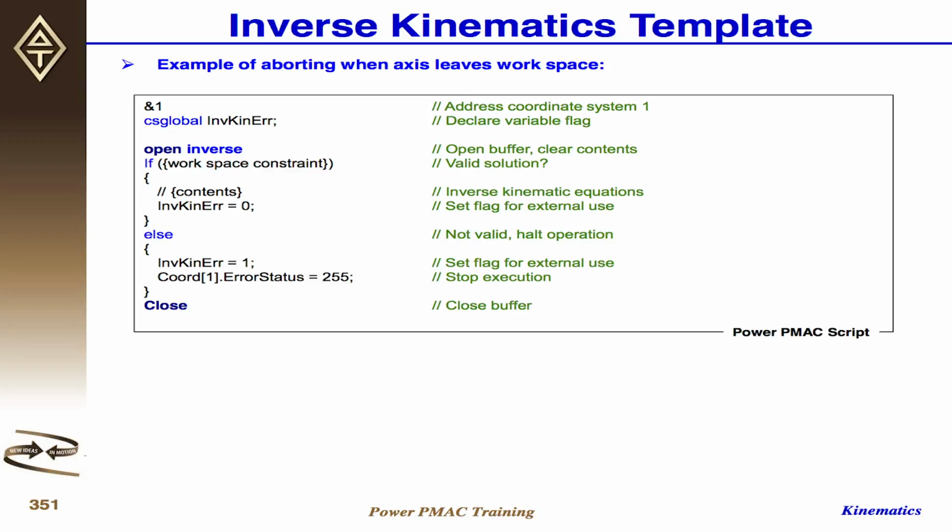Okay? So you have to make sure that you have the logic inside. Make sure that the mapping is one-to-one. Otherwise, because we're getting the position out of forward kinematics, and that's the first position feeding into the inverse, if that's wrong, then the calculation will be wrong. Then you don't know what will output to the motor for the move. Okay?